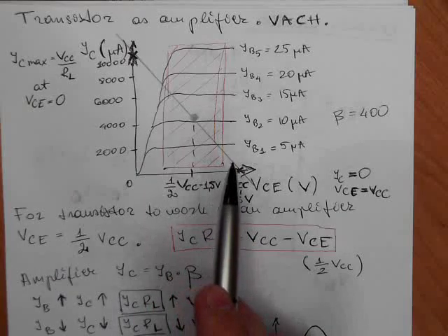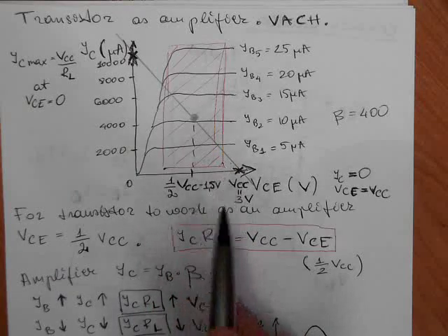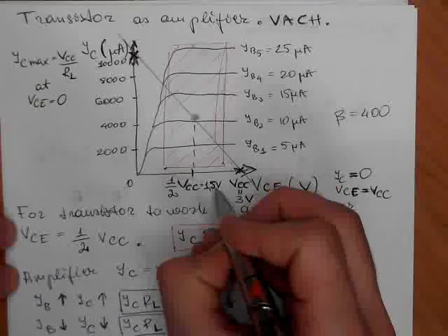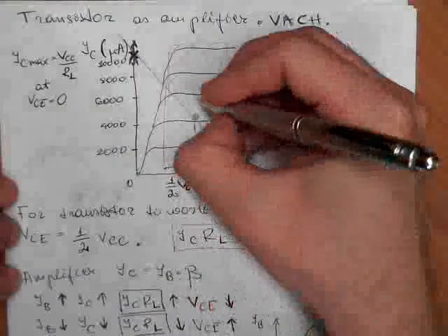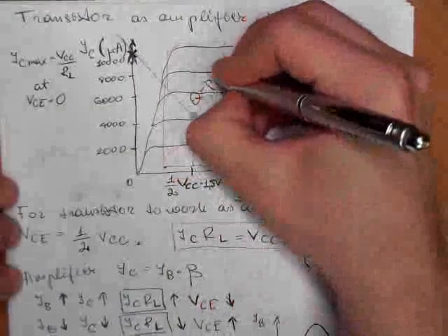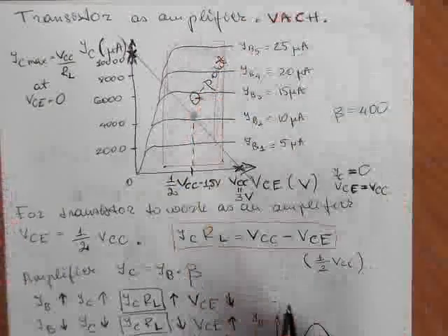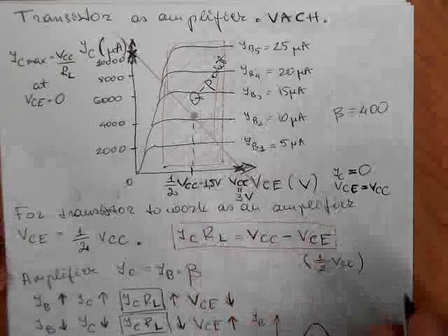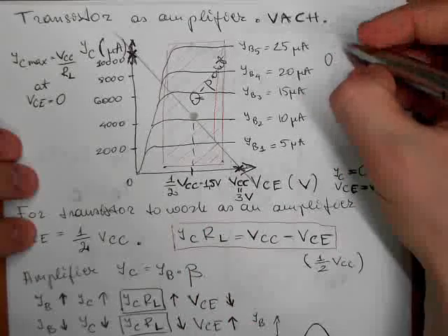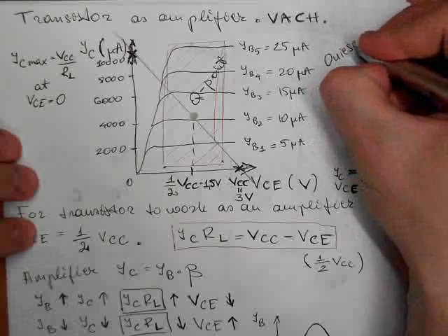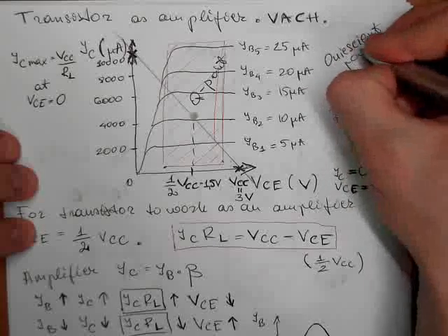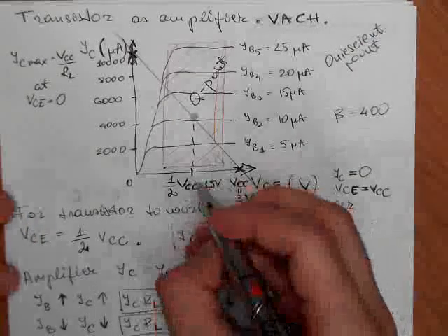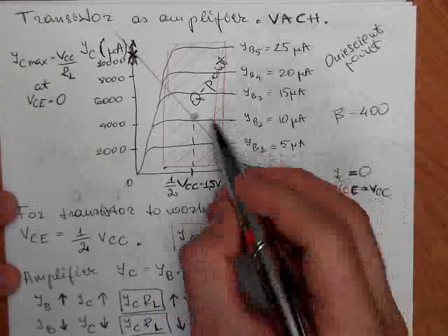But basically the general concept holds here, because here you get 1.5 volts at this Q point. This is called the Q point, the working point of the transistor, operation point or quiescent point. So it tells you at 1.5 volts you take 10 microamps DC base current.